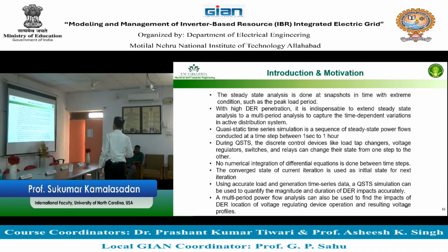So, static time series simulation is a sequence of steady state power flows conducted at a time step between 1 second to 1 hour. Okay, 1 second to 1 hour. So the first step is take the power flow, run it many times, 1 second to 1 hour. Okay, that by itself is not considered as time series power flow or quasi steady state power flow.